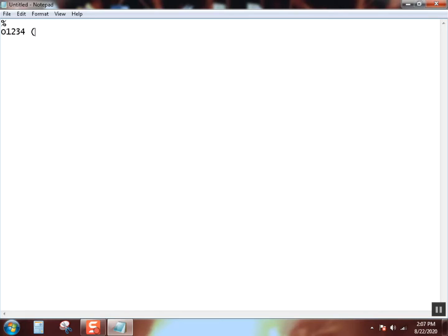Okay. Program name. There we go. So that's great. New line. Next thing we're going to do, so let's highlight. Percent sign always goes in first. Program name, capital O with 4 to 5 digits.